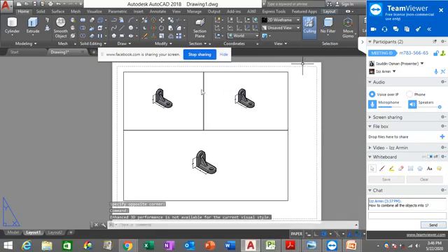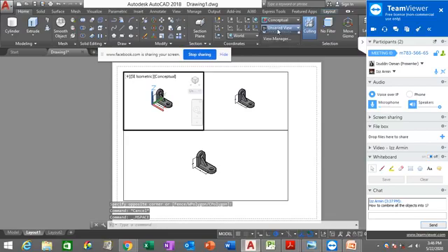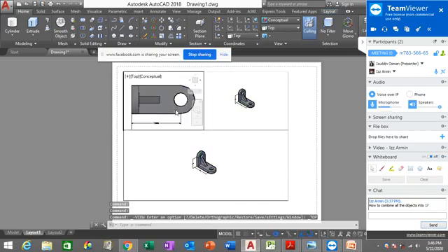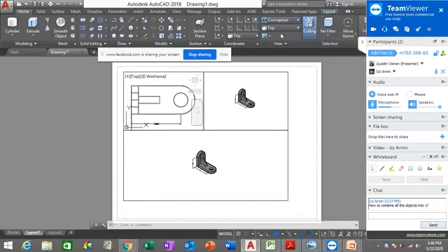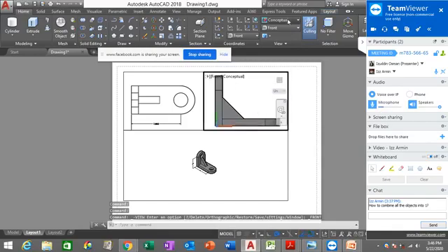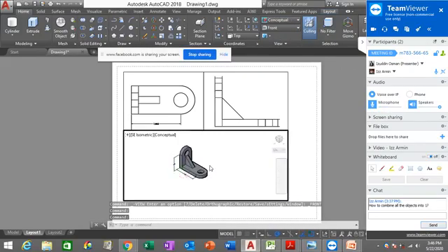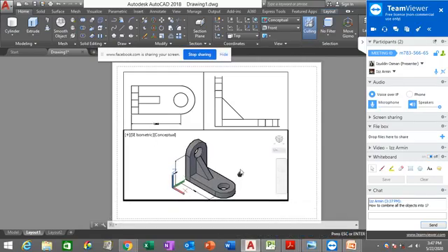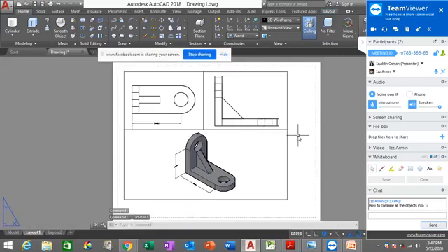All right. So if I've created this viewport and I want to go inside it, I should double click inside the viewport and change this to top. You can see I've changed this into top. You can change the visual style to 2D wireframe. Click this and change it to front view. Alright, front view, and I can change the visual style to 2D wireframe. And double click outside. You can see I can present my object, my model, in 3 separate views on one paper layout. So I have 3 views right now, combined using one paper layout in AutoCAD.